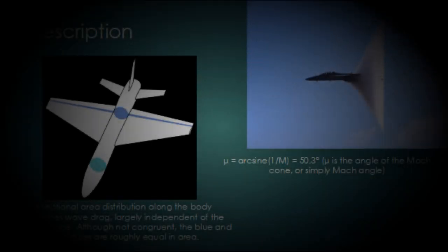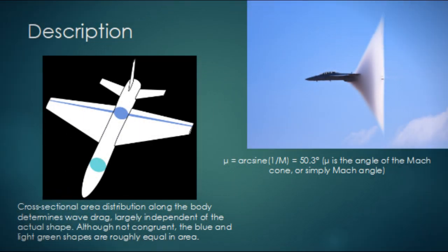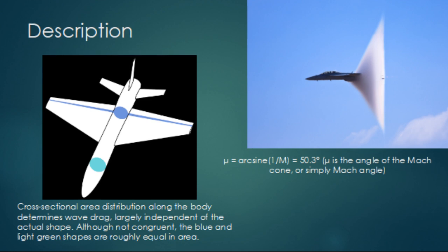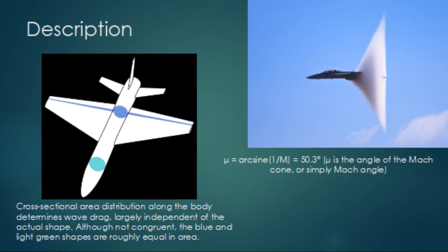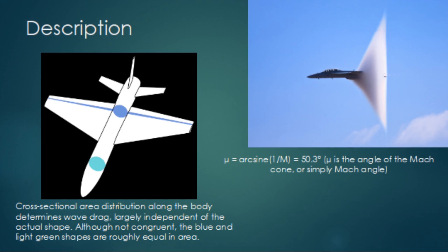At high subsonic flight speeds, the local speed of the airflow can reach the speed of sound where the flow accelerates around the aircraft body and wings. The speed at which this development occurs varies from aircraft to aircraft and is known as the critical Mach number. The resulting shock waves formed at these points of sonic flow can greatly reduce power, which is experienced by the aircraft as a sudden and very powerful drag, called wave drag.